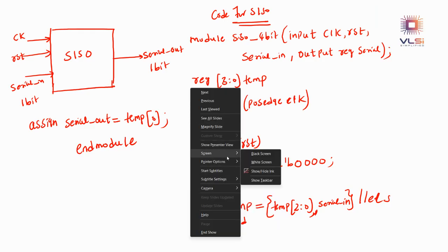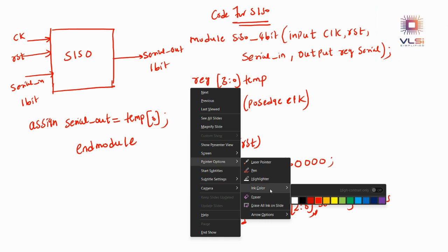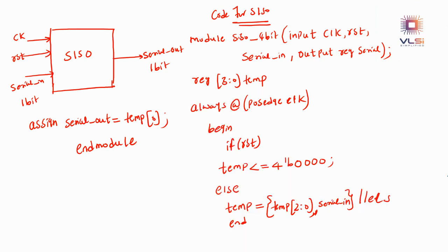Okay, see here. If it is the right shift, what happens? This is 3, 2, 1, and 0. From the left side you are loading the data. So initially all the bits are 0, 0, 0. This is at the initial clock cycle. At the first clock cycle, 1 will be loaded and this will be shifted, and you are getting 0, 0, 0.